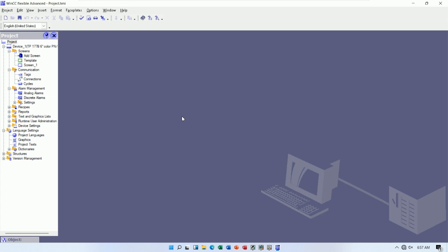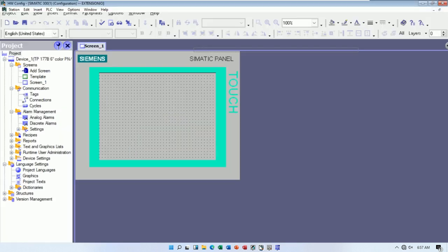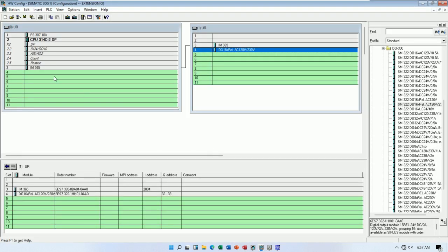It's very important: if we have a big plant, we can use a lot of I/O, right? So we need to extend the I/O, because we have only 11 slots for rack number 0, and if we add more for extension, we can get 11 more slots also. Okay,